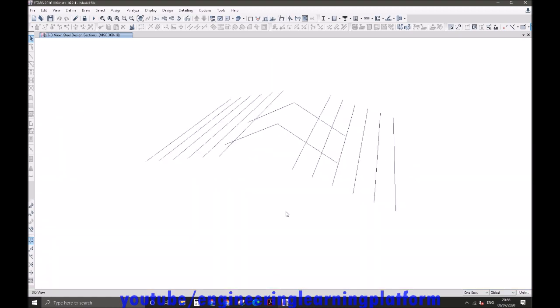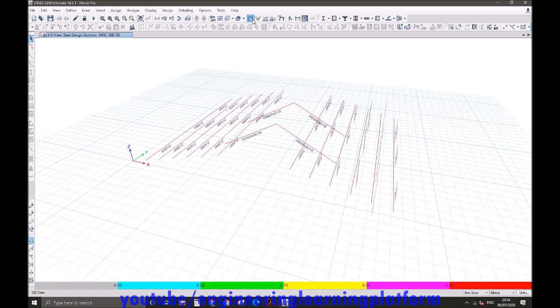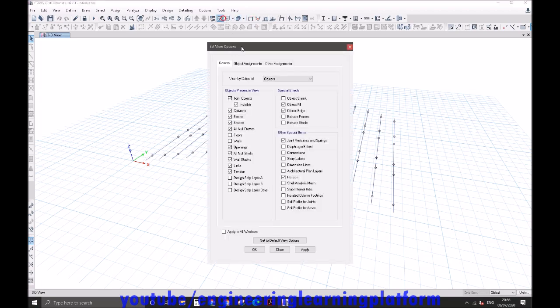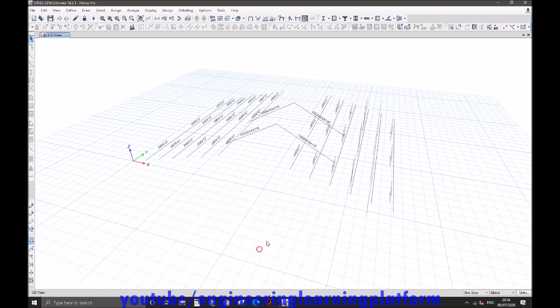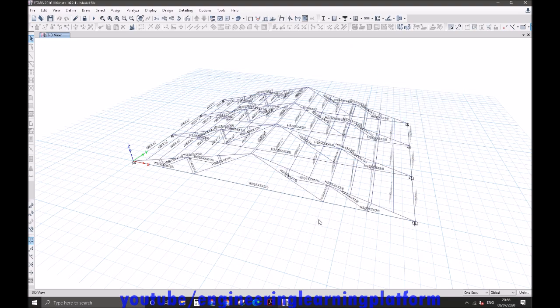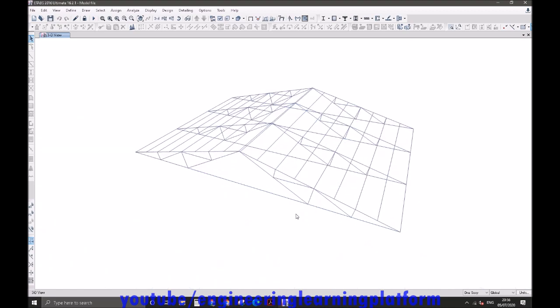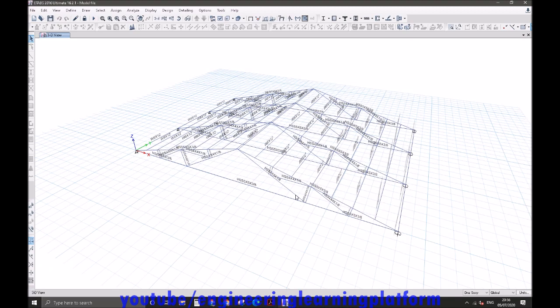So the truss part that is failing is the interior chords, not top chords. I suppose they are not top chords. Yes, they are still hollow tubes of 4 inch by 4 inch section, so we must increase their size.